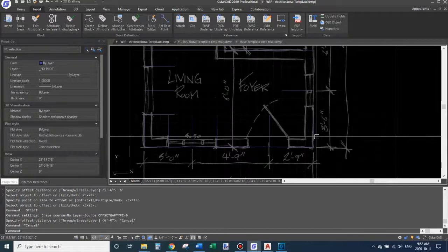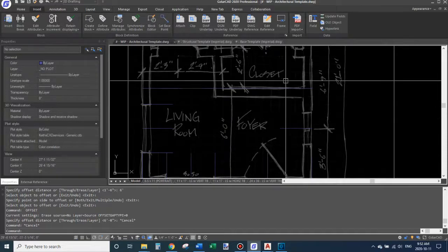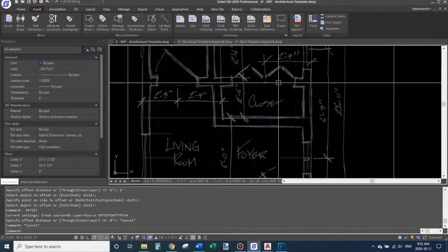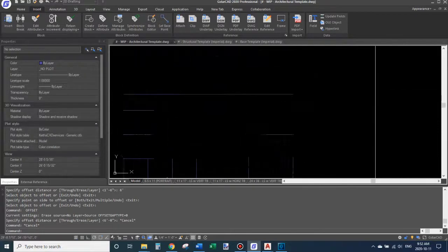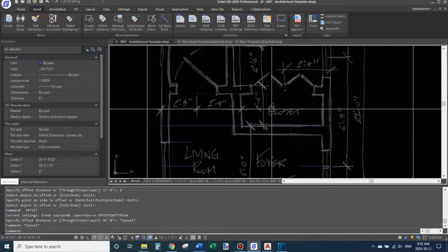They don't usually go on the siding, because if you have like lap siding or hardy board, it's kind of arbitrary where to take that measurement from, but the sheathing provides a nice concise surface to take your measurement from, and then of course the framing as well. But probably what I'm going to do is place my exterior dimensions on the outside of the sheathing, and then my interior dimensions will go to the middle of the walls.